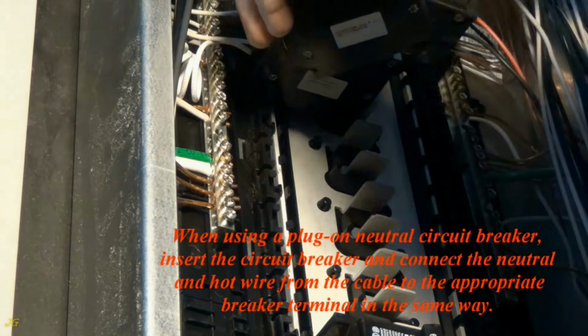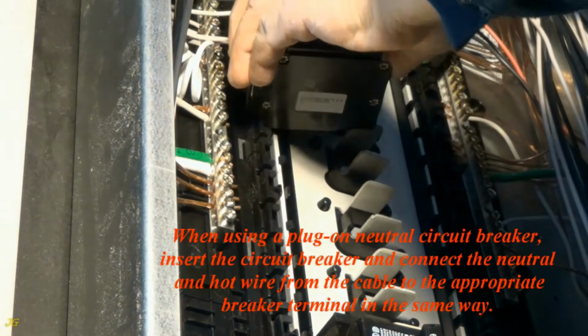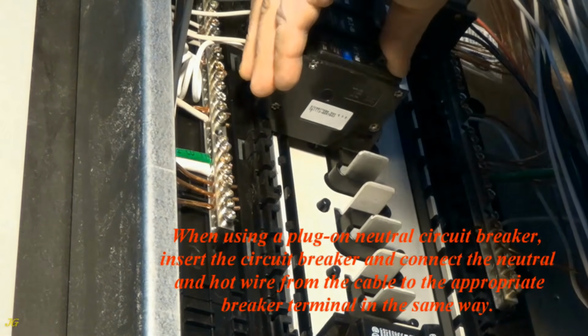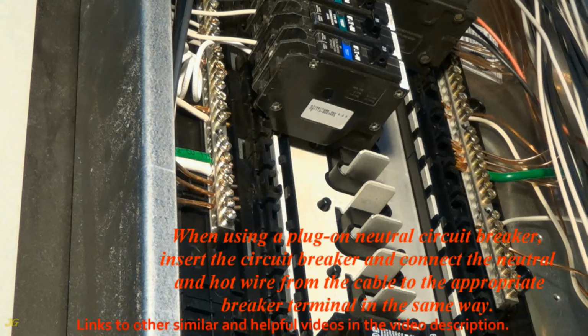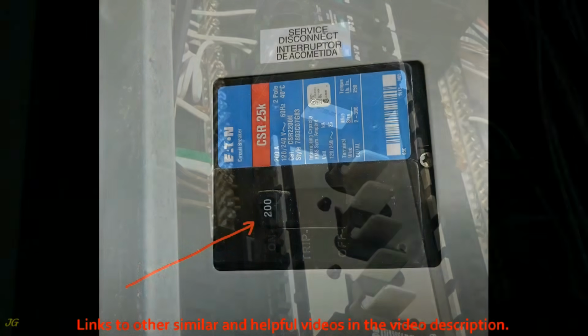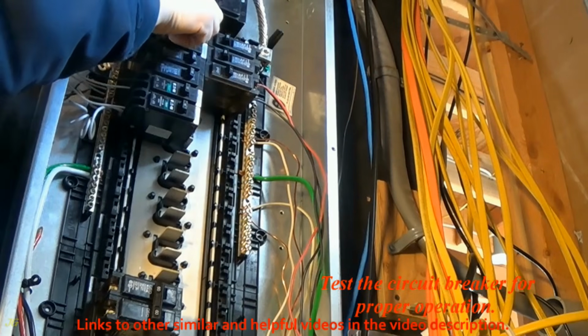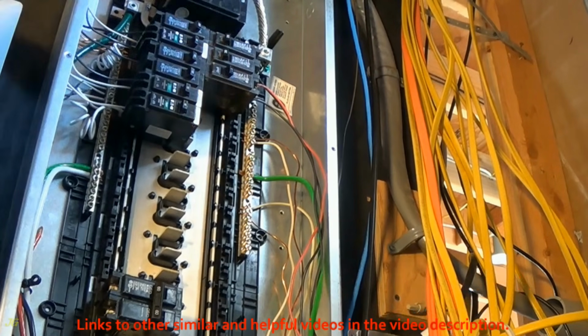When using a plug-on neutral circuit breaker, insert the circuit breaker and connect the neutral and hot wire from the cable to the appropriate breaker terminal in the same way. Restore power. Test the circuit breaker for proper operation.